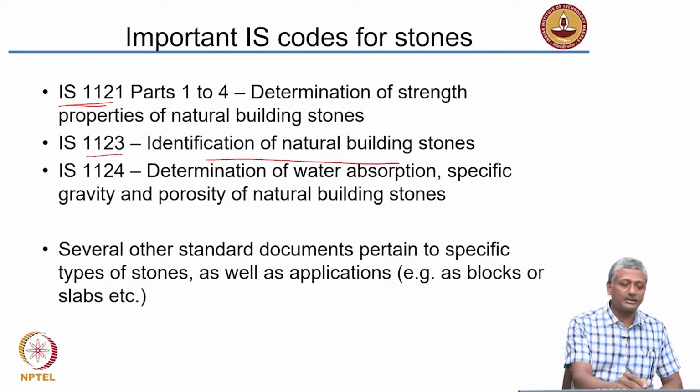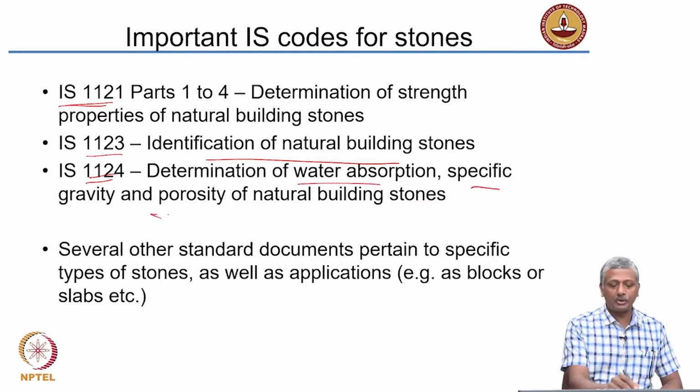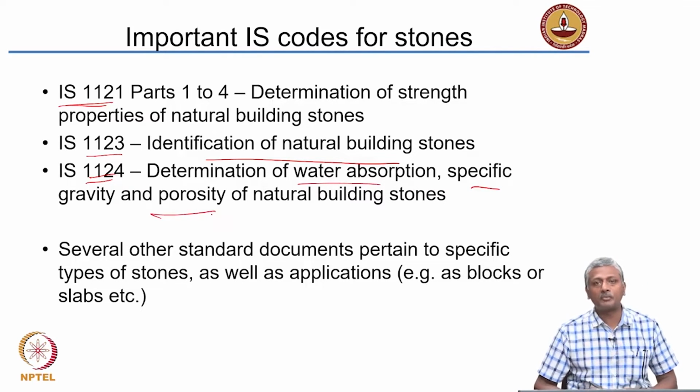And then of course the other test parameters are water absorption, specific gravity and porosity. Those are also very important from the point of view of engineering applications of the stones. So that is covered in IS 1124.